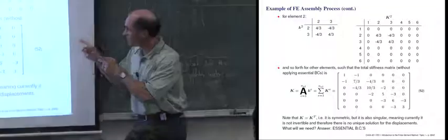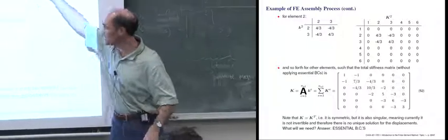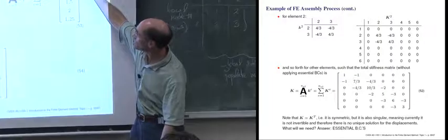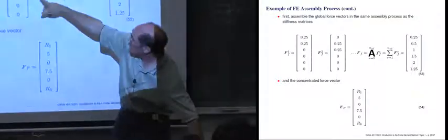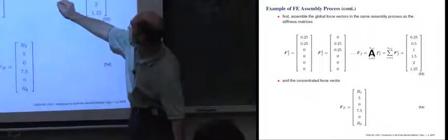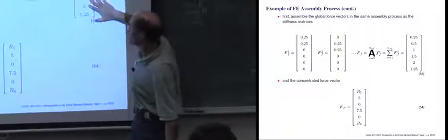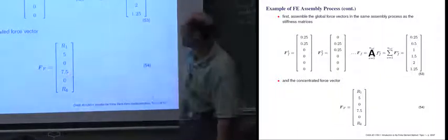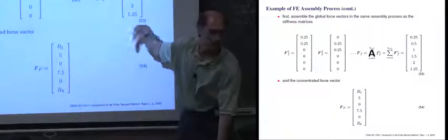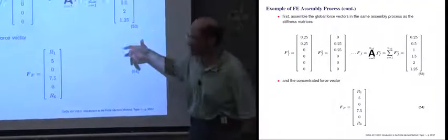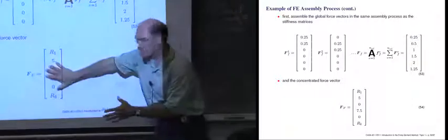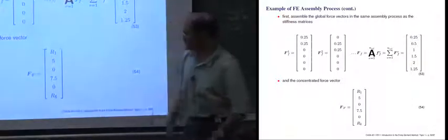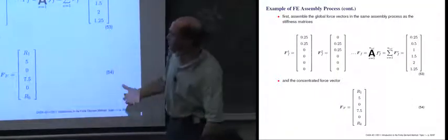I think, though, that we first need to apply the same thing that we just did with stiffness, do the same thing with force. So just do the same thing with the forces, put them in their locations. The assembly operator comes to a sum like this. Same for the concentrated. You'll see we get back the 5 and the 7.5. I told you that's what would happen. Eventually, what you'll see for the next example is we go directly to this matrix. We don't break it up into its little pieces. We start to gain some confidence in how to do this.